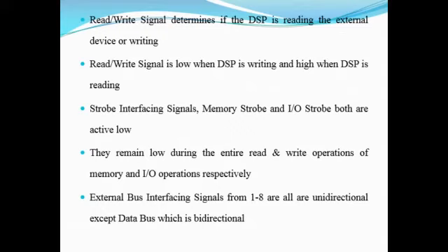So whenever we consider the strobe interfacing signals, either memory or IO strobe, they are always kept low during the entire read and write operations.